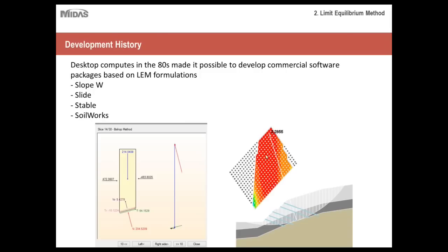And just using these programs, they can easily calculate multiple arc surfaces or slip surfaces. They can automatically compute all the forces that are acting on each slice. And most programs will actually isolate your minimum factor of safety for you. So it's very convenient.